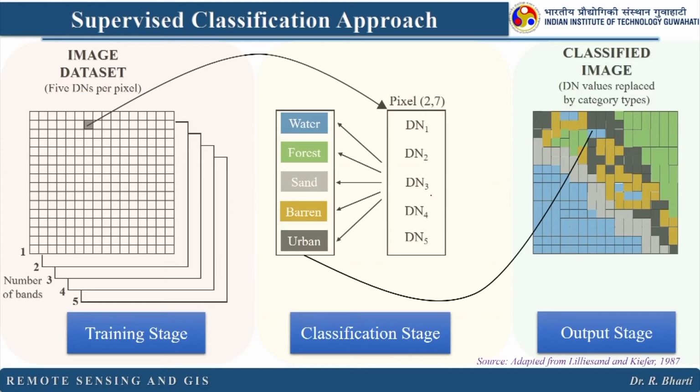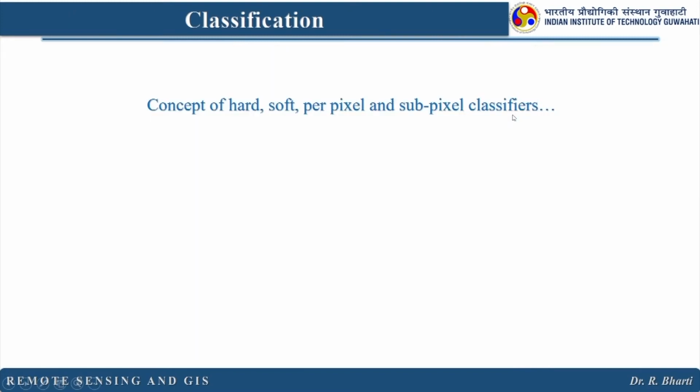Now here I just wanted to highlight what is the complication when we use hyperspectral data. When you are having a 4 or 5 band image, then you have only those 5 values for each pixel, right? But when we are having hundreds or 200s or 300s bands, then for each pixel you are having 300 values, right, in different wavelength regions. So how do we exactly perform this classification? That is based on some spectral classifier.